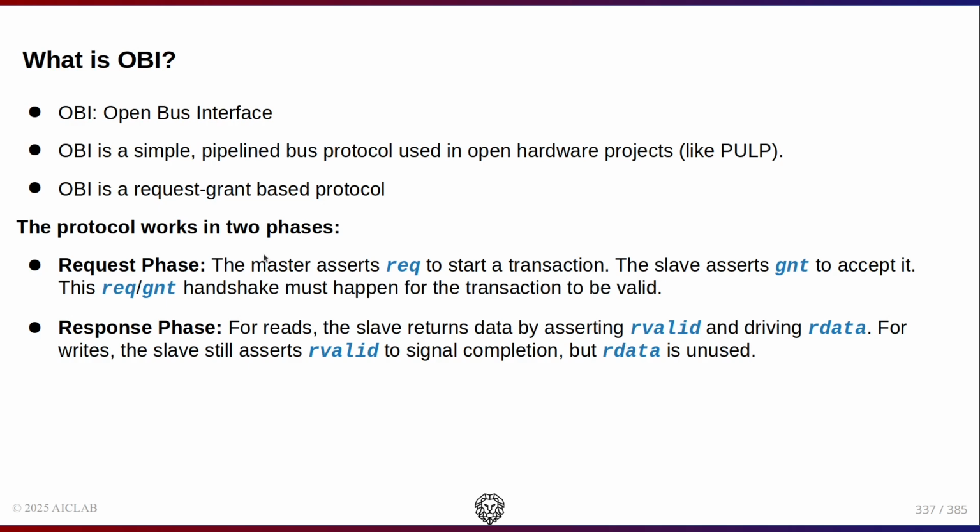In the request phase, the master initiates a transaction and the slave accepts it. In the response phase, the slave signals back that either the requested read data is ready or that the write operation has been completed.